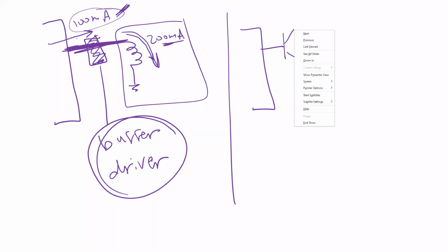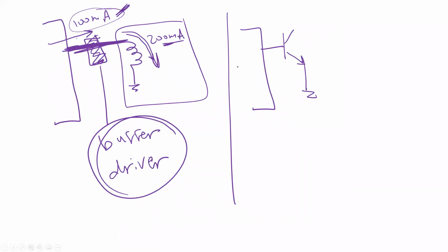And then the coil is here. You put the coil here, okay? So what happens here, guys, you know the base current is a small current. So if I output 5 volt here, the transistor is on, the transistor is a short circuit, and we are going to get a small current from here. And then you know the collector current is much bigger than the base current, okay? So that's exactly what you are going to see right now.